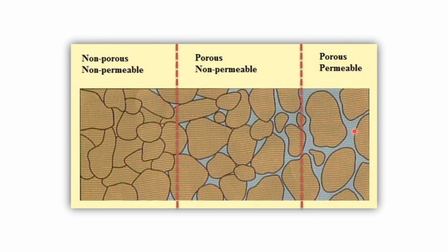So if the moisture content is 0, that means the well is dry. If the moisture content is 100, then the well will be recharged soon. The measurement of the moisture changes may be done by neutron logging, just to understand and to determine the specific yield. There are a few geometric factors that are also considered before doing a well logging.